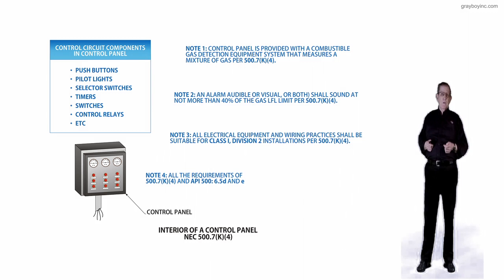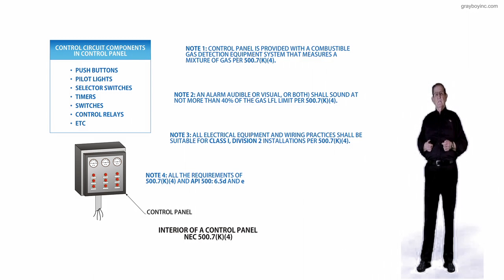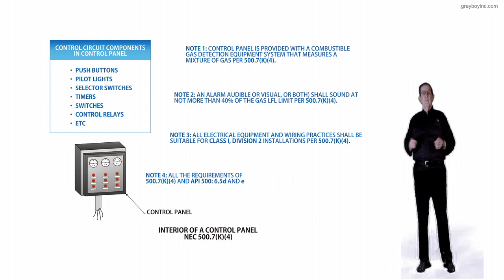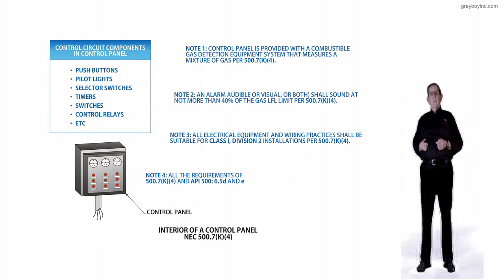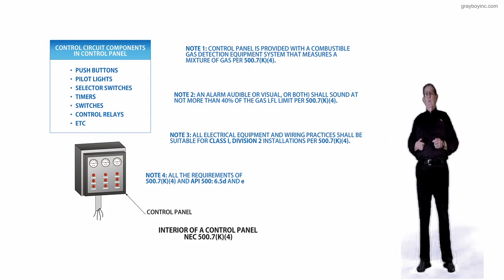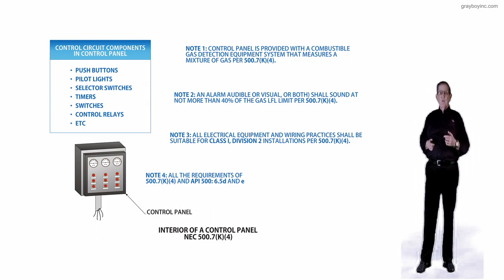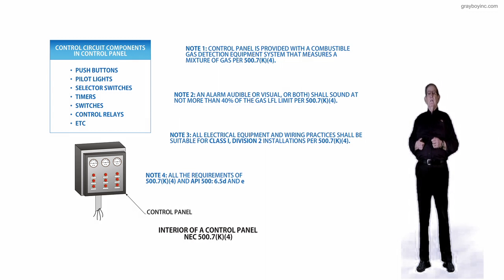And then we know Article 409 coming out the gate, and 409.1 would refer you to UL 508 to look these up, these additional requirements of separation based on voltage, etc. So keep that in mind. Now, if we want added protection techniques that we might want to use, just review 500.7 (L), (M), (N), and (O), which these methods would be defined in Part 3 of Article 100.